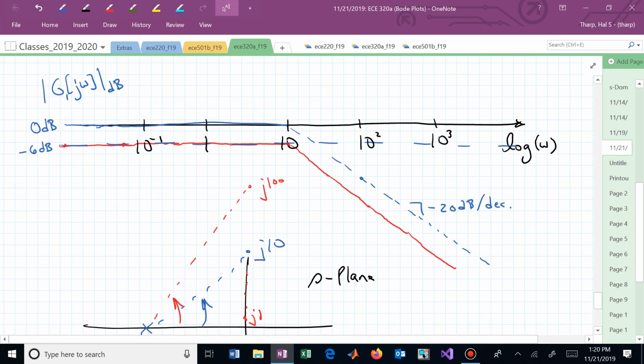And the magnitude is right there. And that's going to be at minus 26 dB, and you would have to then convert that to an actual numerical value from dB, but you would just say, oh, 20 log of some number, A, is equal to minus 26, and solve for A. And that would be the scale factor.